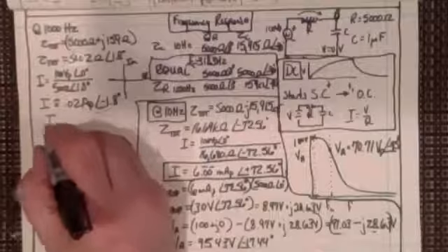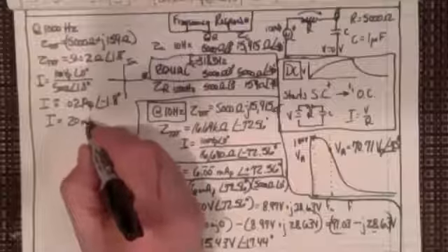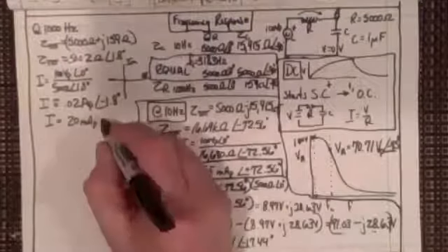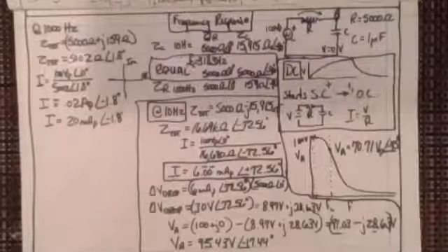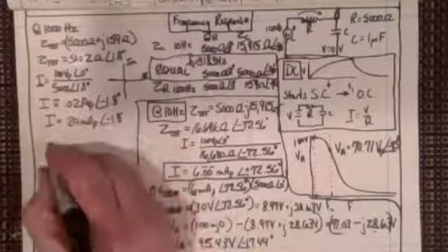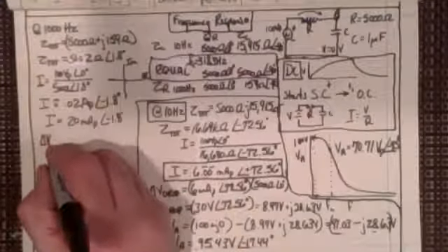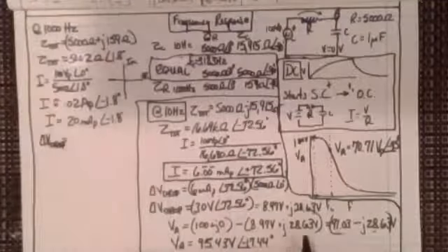So that's my peak. Now, look at that. If we write I, this is 20 milliamps peak. 20 milliamps at minus 1.8 degrees, right? Now, 20 milliamps is a heck of a lot more than 6 milliamps, isn't it? So all of a sudden, we find that voltage drop across the thing. And in fact, we get hit twice by it because we don't get the extra whack we did here by squaring 28.6. We're not going to have anything like that here, are we?